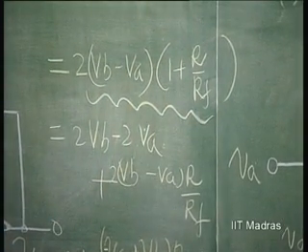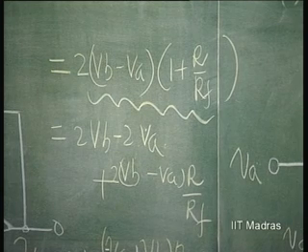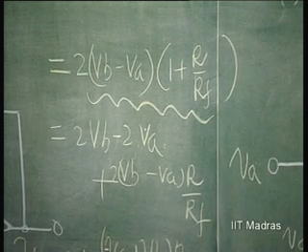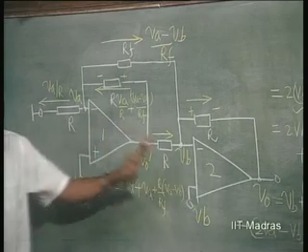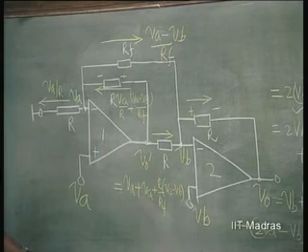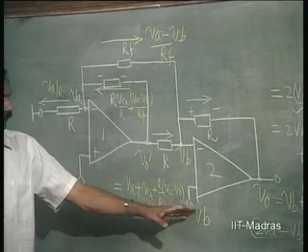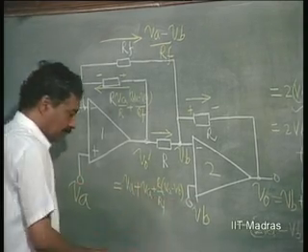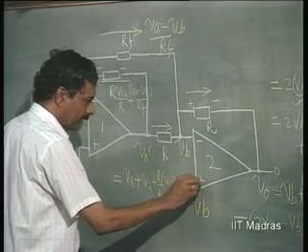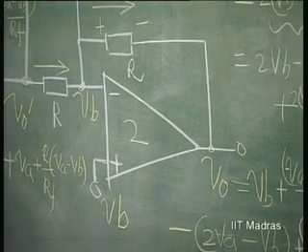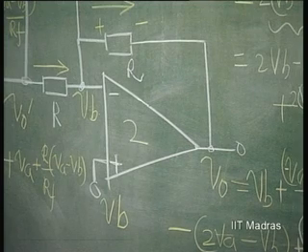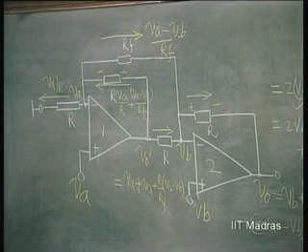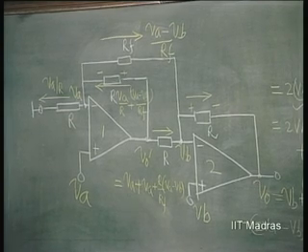So, once again we see that this is going to act as a differential amplifier, but uses only 2 op amps, and buffering action is still there because these are the non-inverting terminals here to which inputs are fed. Okay. So, these 2 instrumentation amplifier configurations are quite popularly used in practice.